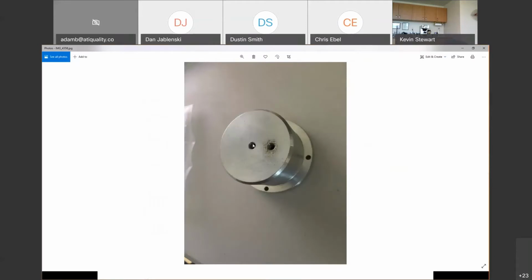So we're going to set our origin to the center diameter and skew between the two diameters to get our system set up so our datum structure is correct. And then it calls out true position to 4 holes at each. I always joke and say the corners of the diameter here, but every 90 degrees there's a circle there.